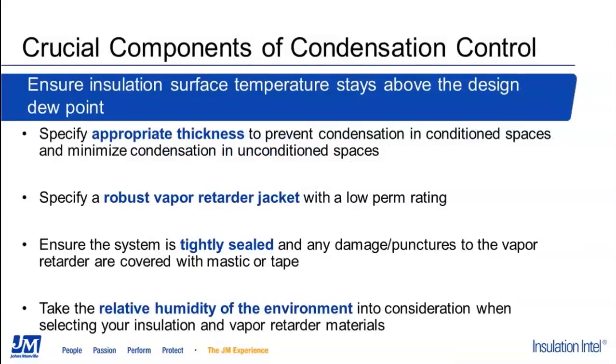I mentioned that condensation control is a key reason for why to insulate a chilled water system. In order to properly control condensation, you need to make sure the surface temperature of the insulation on the chilled water system is going to stay above the dew point. And that's determined by the ambient air temperature as well as how much moisture or humidity is in the air.